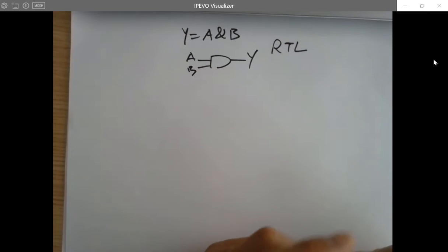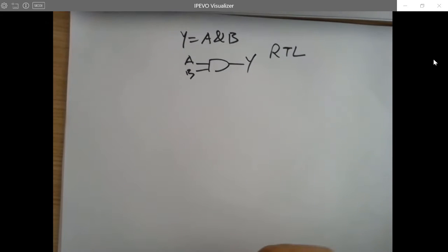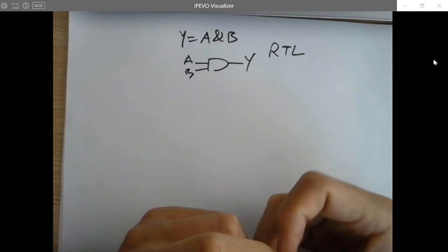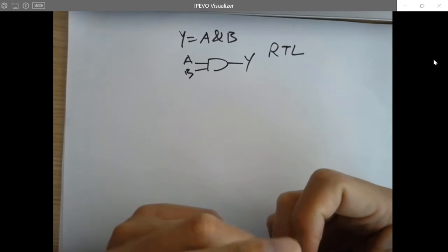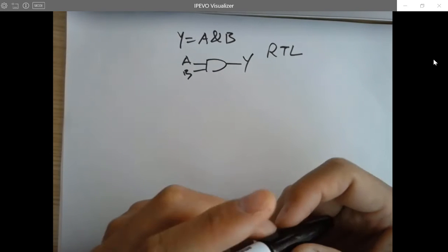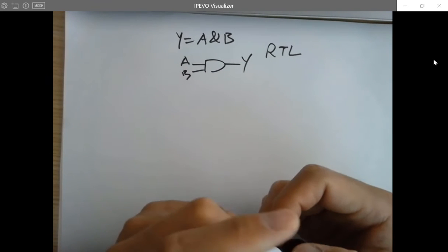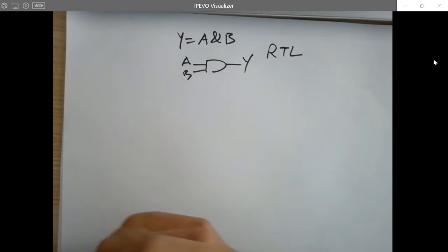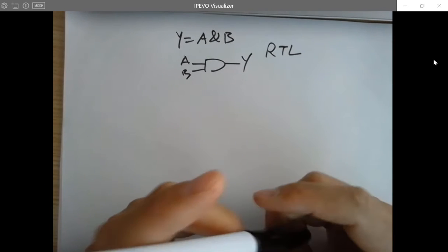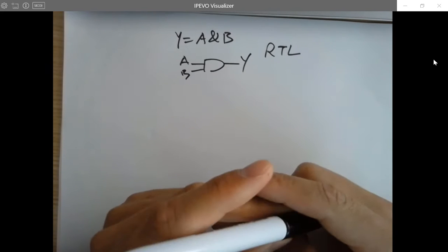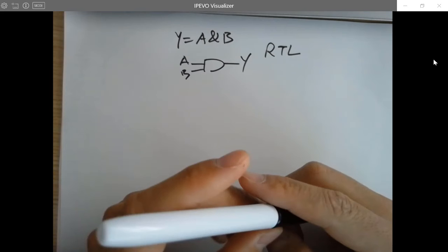But for the 40 nanometer technology, the ESP32, I don't believe it's able to handle that 20 volts power supply easily. So that's why, and also, as a high performance microcontroller, it needs a lot more memory or flash to store their programs so they can run a large scale design. So that's why the flash of ESPs is off the chip. It's another IC just beside it.